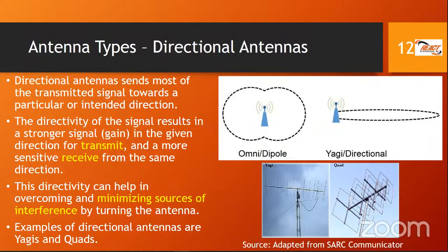But for HF, you could have an antenna on the ground and it will radiate. So really in terms of the HF, it's not either or. Not that you can't do it, but optimally VHF and UHF antennas are put way above the ground, above all objects and so on. But for HF antennas, there can be designs where you have them right on the ground, ground mounted, exactly as you saw in the picture. So the four sloped radials are usually for those VHF, UHF type antennas. And the HF antennas tend to be ground mounted with those radials.